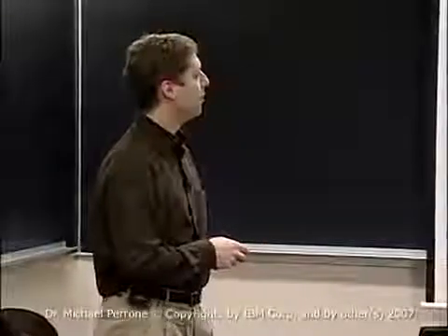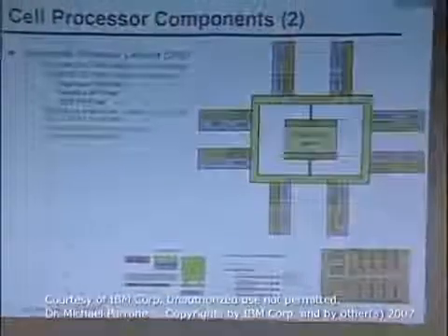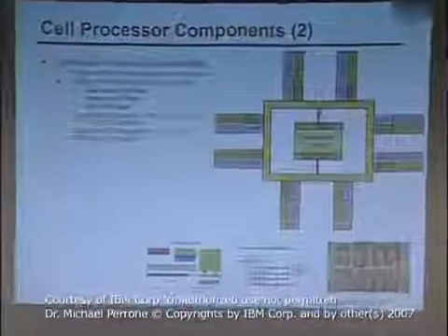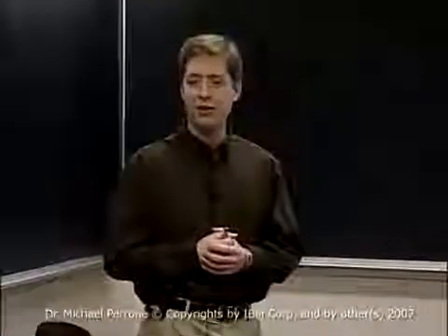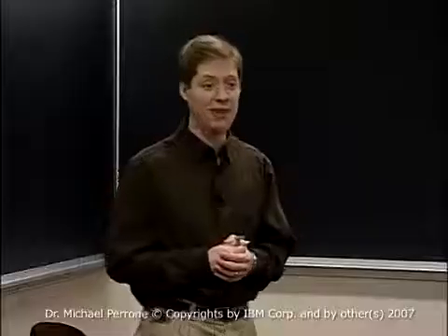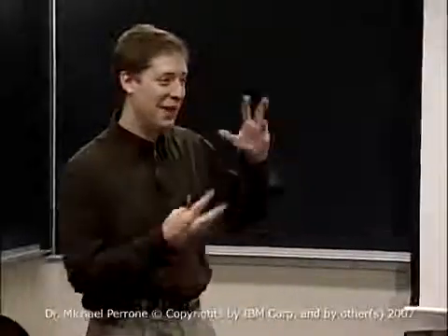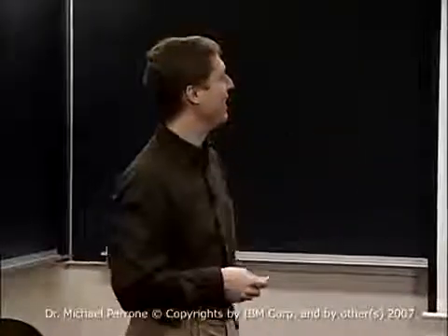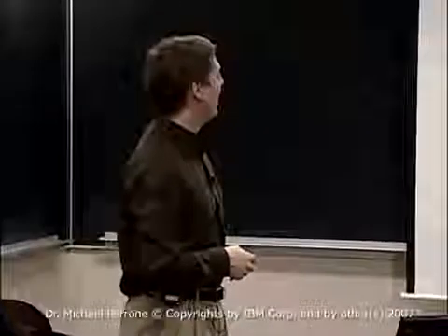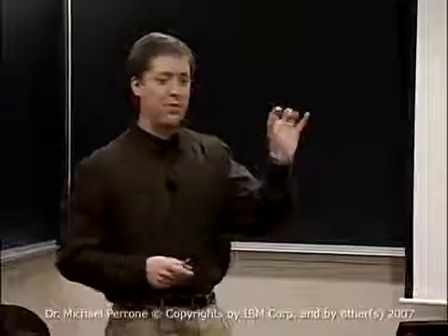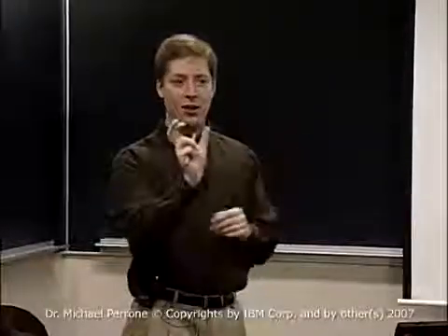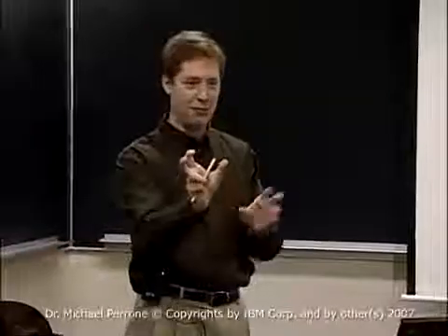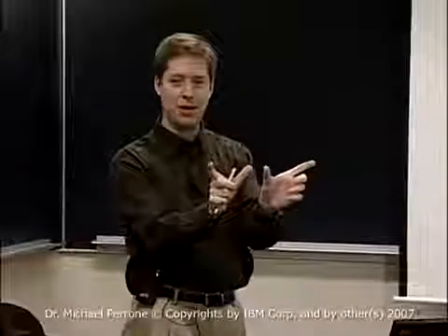It has IEEE double precision floating point, but it doesn't have IEEE single precision floating point. It's a curiosity, but that came from the history. The processor was designed for the gaming industry, and the gamers, they didn't care. They didn't want IEEE. Who cares about IEEE? What I want is to have good monsters on the screen. And so those SIMD registers can operate bitwise, on bytes, on shorts, on 4 words at a time, or 2 doubles at a time.